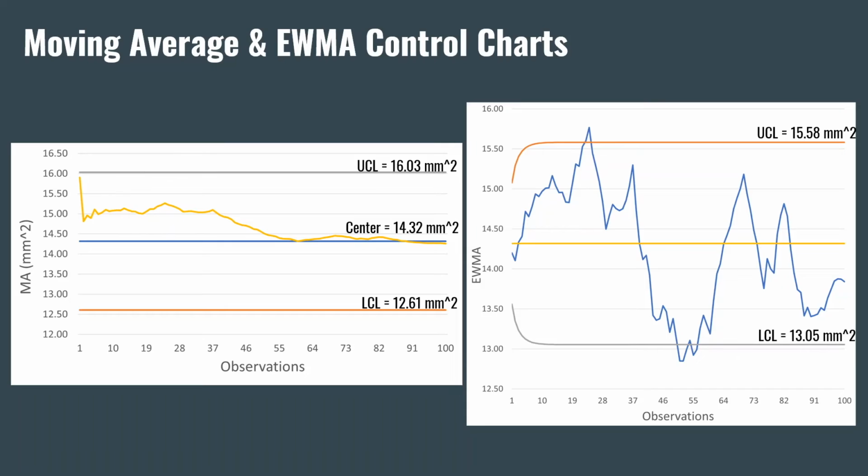In comparison, the exponential weighted moving average or EWMA control chart puts more emphasis on the previous weighted average of all previous samples, so it will be even better at detecting small shifts. Most data points are within the upper and lower control limits of the EWMA chart, although there is an unpredictable trend line for the next process mean shift.